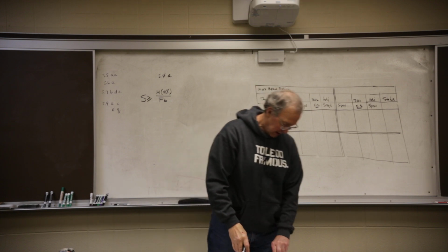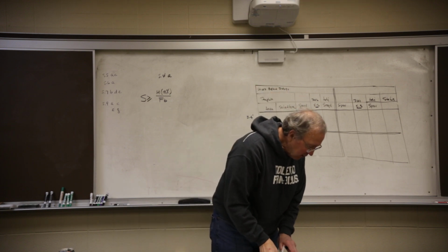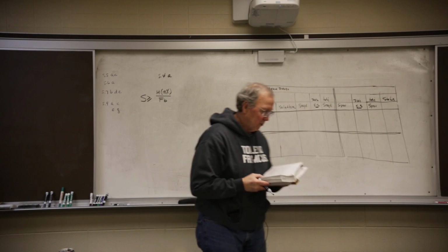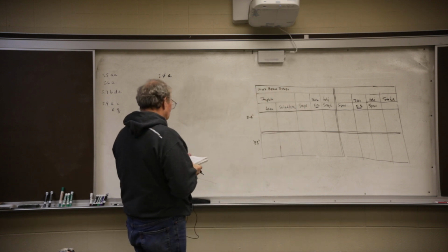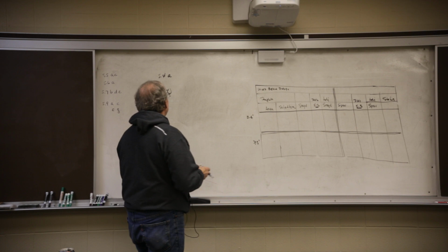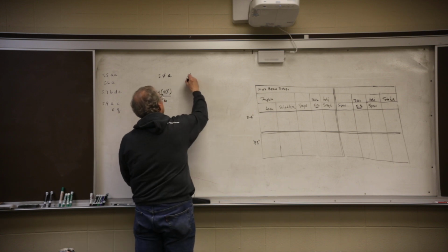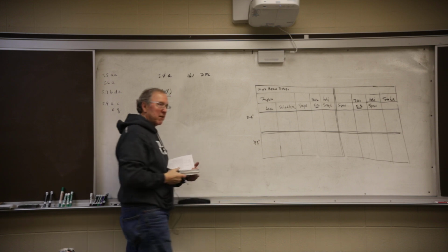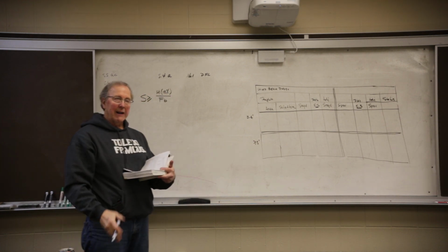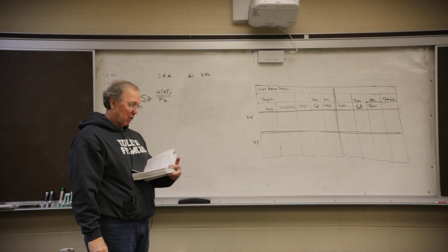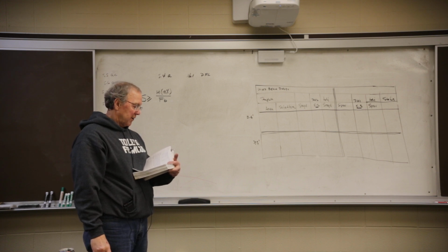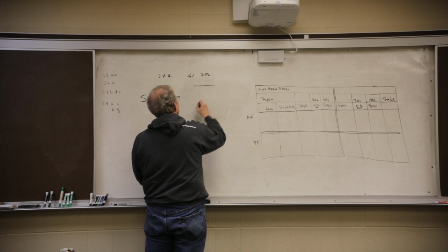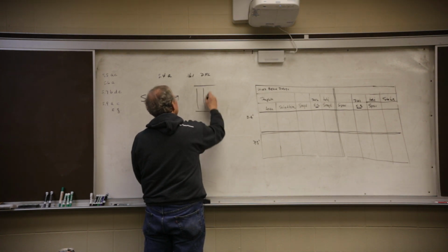So let's go to the page. The equation that you need is on page 204, of course. So let's go to 5.4a. It says I've got number one grade, number one Douglas fir-larch. Why is that important? I got to use it to get the right value out of the table. A series of floor beams that are 6 foot on center. So I got these beams that are placed at 6 foot.